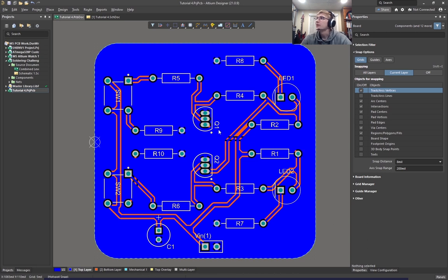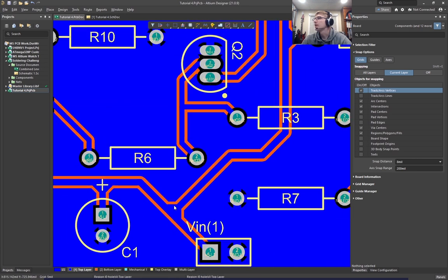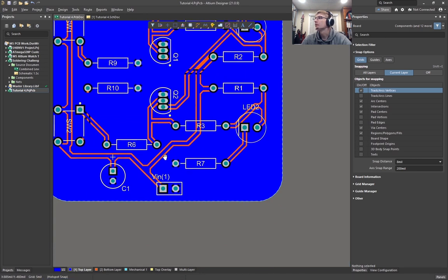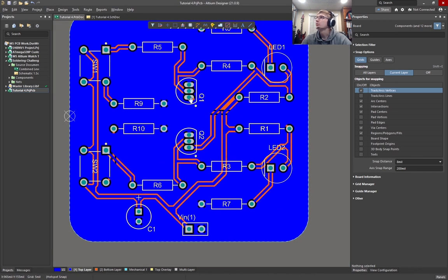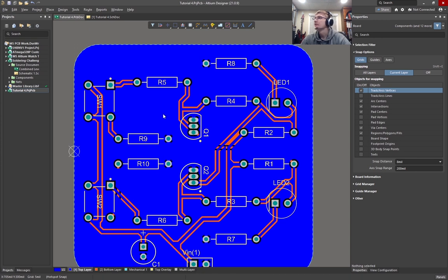And so last time we finished the routing, we fixed these 90-degree corners, we filled in all the dead copper with a ground connection, which poured across the entire thing. So where do we go from here?